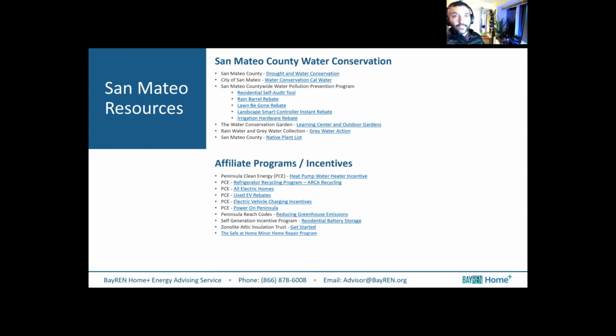I'm personally a Mastic fan, and Mastic is a peanut butter consistency latex goop. It comes in a 3-gallon bucket. You put on dishwashing gloves, stick your hands in it, and slop it on and around whatever you're trying to air seal. Once it dries, it expands and contracts as the heating system expands and contracts, and it doesn't crack or break away. Same thing with air sealing of the house. So I'm a big fan of Mastic. It's hard to find contractors that always do it, but there are definitely people out there.